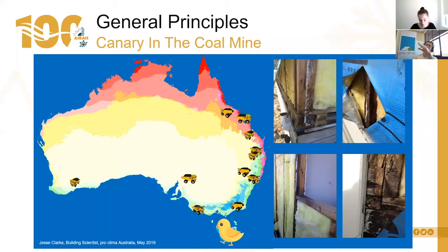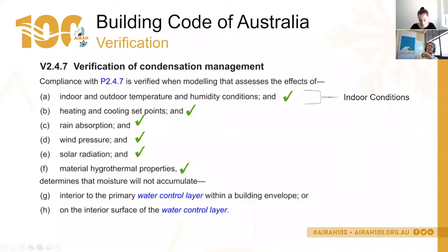But it is essentially bad news in terms of moisture design and trapping moisture in the building fabric. Tasmania is doing a good job in trying to turn that around and come up with better construction systems that actually work in those climates. As we increase energy efficiency across Australia, there may be worse problems emerging in climates up to the higher latitudes.